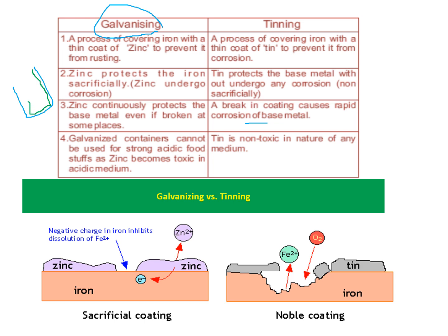If you keep some pickles or many other things, some pickles having acidic nature, H plus ions are there. In the presence of H plus ions, the zinc is involved in corrosion. We already know wet corrosion in an acidic medium releases H2 gas and zinc dissolves as Zn plus 2. That means Zn plus 2 comes into your food items, you will consume that, and it leads to illness. That's why galvanized metals are not suggested for storing food materials.